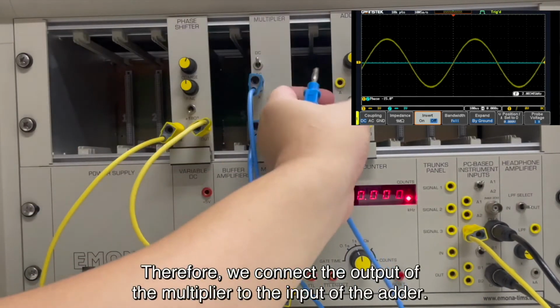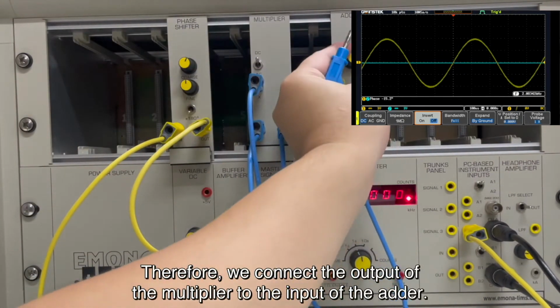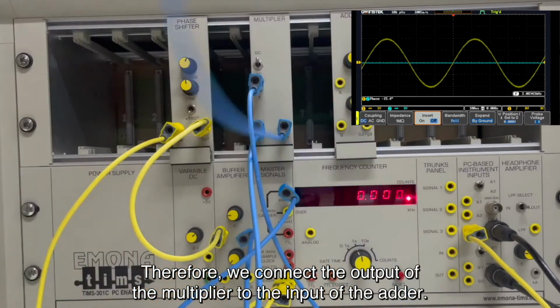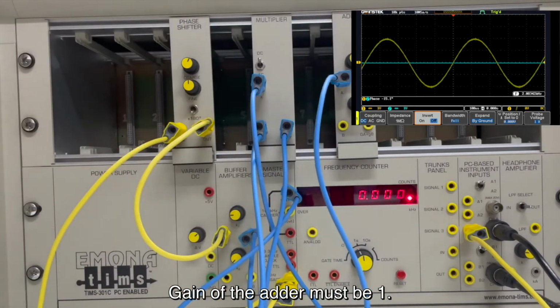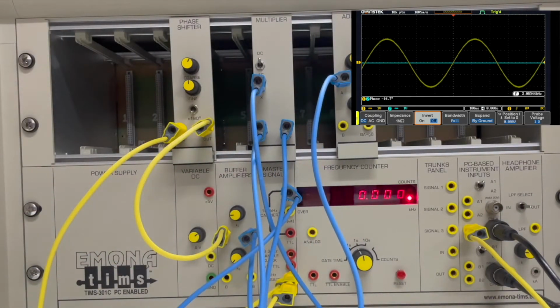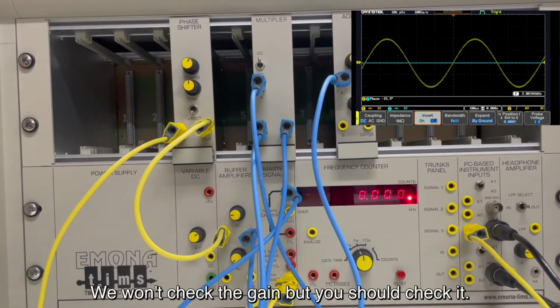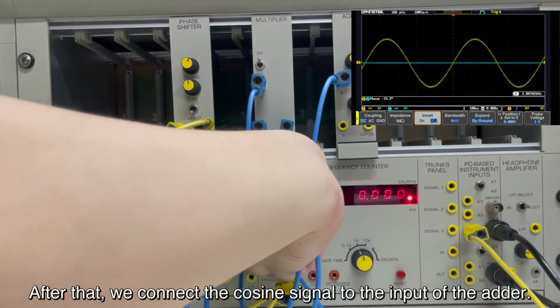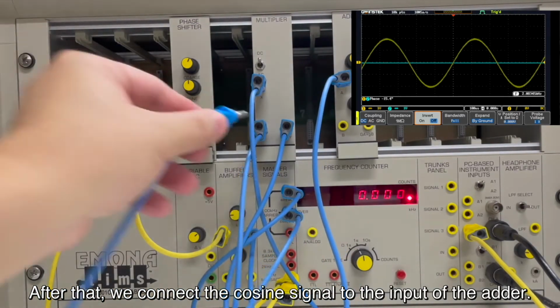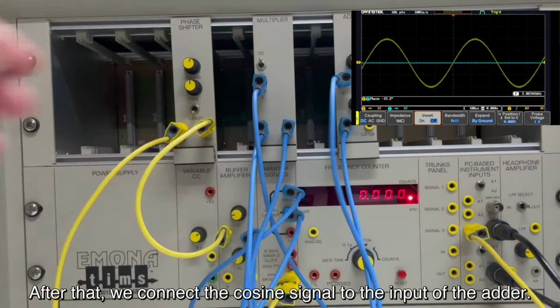Therefore, we connect the output of the multiplier to the input of the adder. Gain of the adder must be 1. We won't check the gain, but you should check it. After that, we connect the cosine signal to the input of the adder.